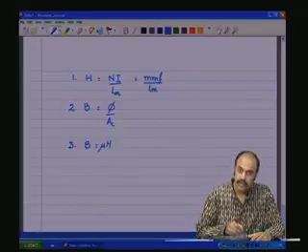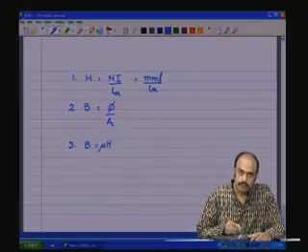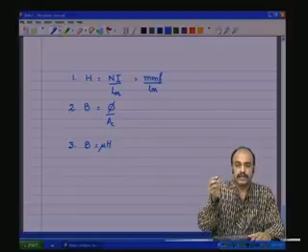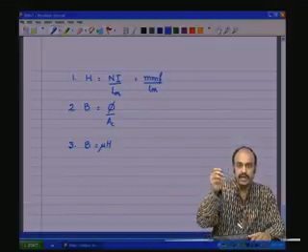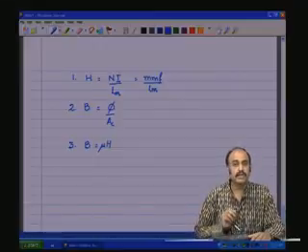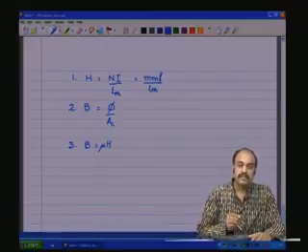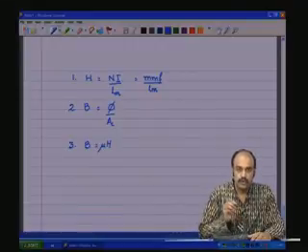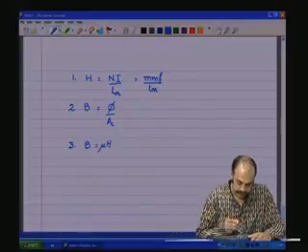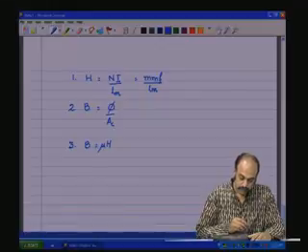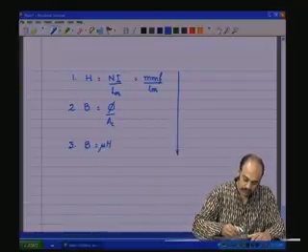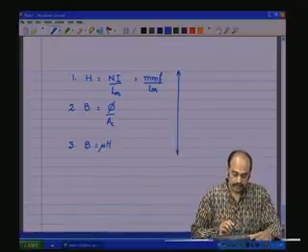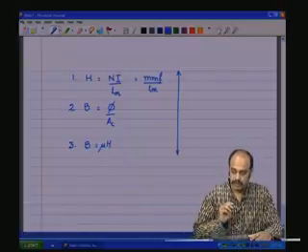Mu is a constant. However, in a practical core, mu is not constant, as we saw that it exhibits hysteresis. The BH curve exhibits hysteresis. Mu is varying from point to point, so it depends upon the operating point. It is more or less linear close to the 0 operating point. So, these three relations govern the operating principle of the transformer.